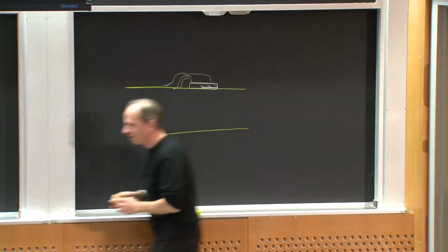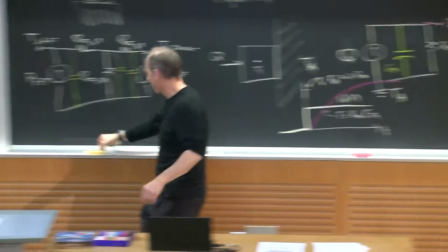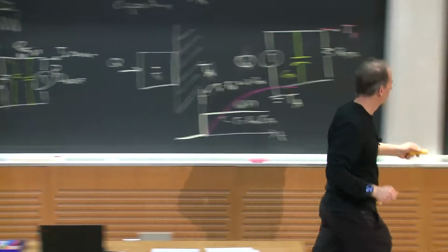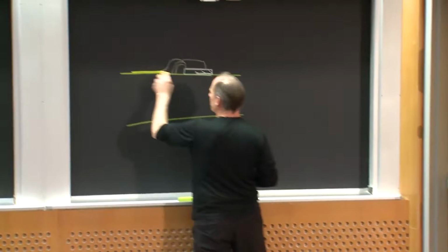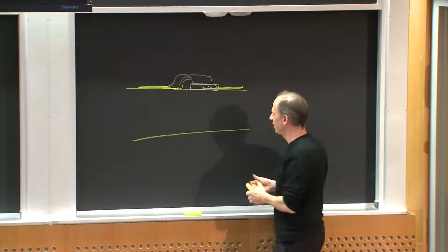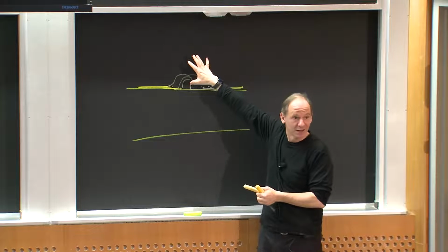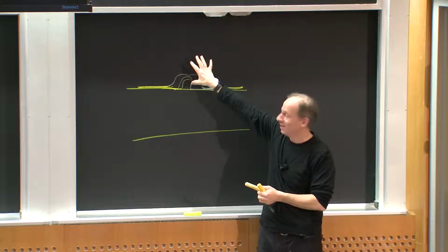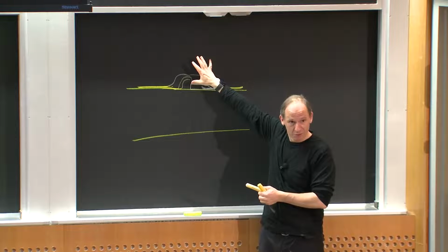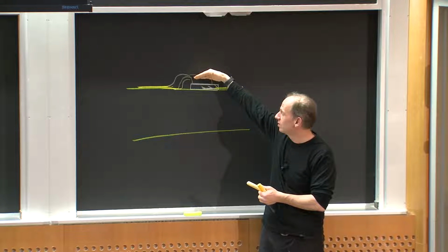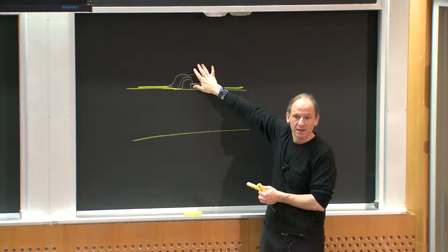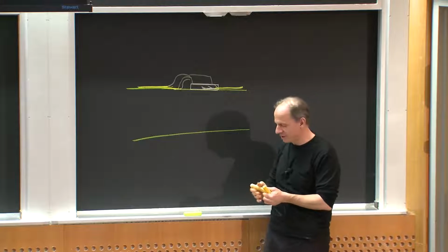And my electrical connections would come off of that, right? I'd run my gate and my source. I'd have a bunch of wires on the circuit board going different places. So I've made my electrical connection to the device, but now I also need to get the heat out of it, right? So what do I do? Often, instead of trying to mount the device directly against the heatsink, you mount the device to the board, carry the heat through the board, and then to a heatsink on the other side.